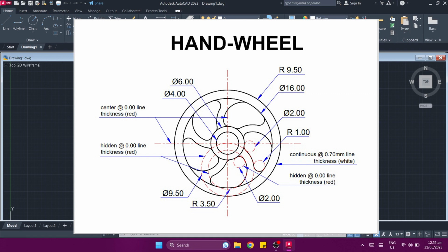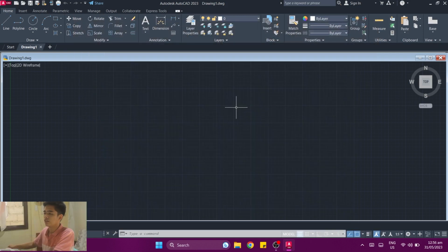These conditions are what we call layer properties, which refer to a feature in AutoCAD that allows you to give unique properties and settings to individual layers inside your drawing. Each layer can have its own unique properties, such as color, line type, line weight, transparency, and plot style. That is what we would officially start to work on first.